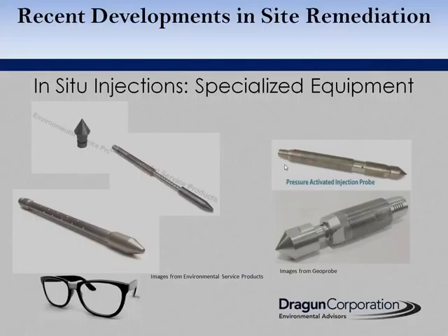The other four tools that you see on this slide were developed in recent years to aid with lateral injection of oxidants. These tools allow the oxidant to be applied over a specific depth range or zone of contamination, typically between 2.5 to 12 inches. Some lateral injection tools are activated via pressurization, which is shown in the two photos on the right of the slide, and others are simply an injection screen in a retractable sleeve that is opened by pulling up on the drill rods.